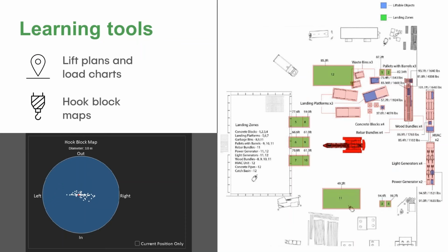So if you are into cranes, we try to mimic as much as possible what the real cranes are experiencing. We don't want to set the idea that you get on the crane, you load it up, it's already set, your LMI is set, and you're going to start moving things. No, you're forgetting 50% of their job, which is lift planning and load charts and setting up your crane, and that's what's more important.